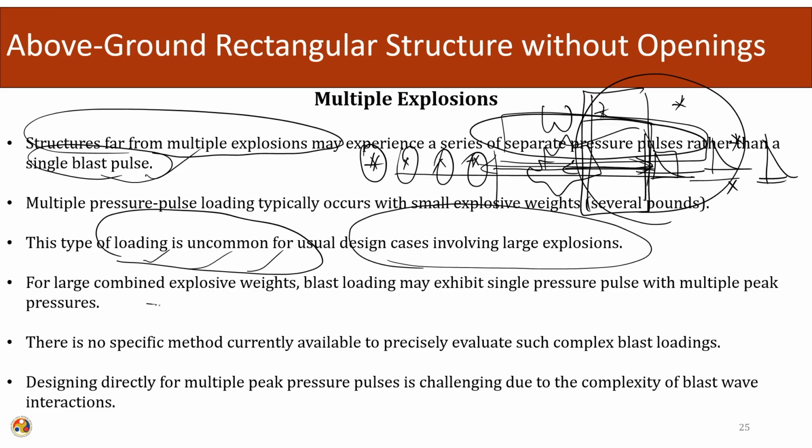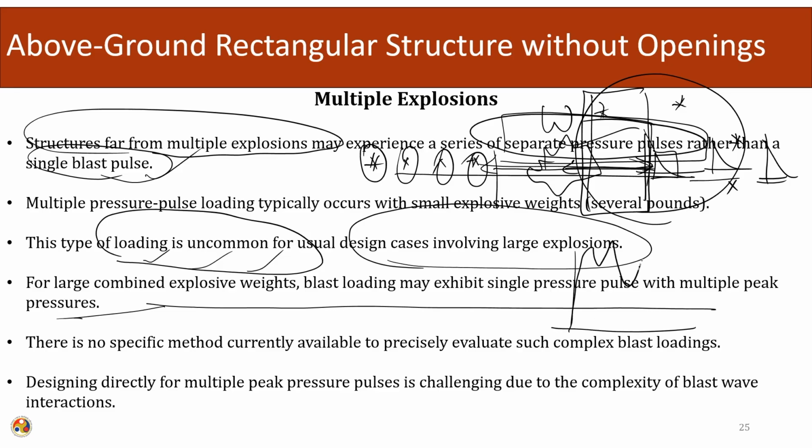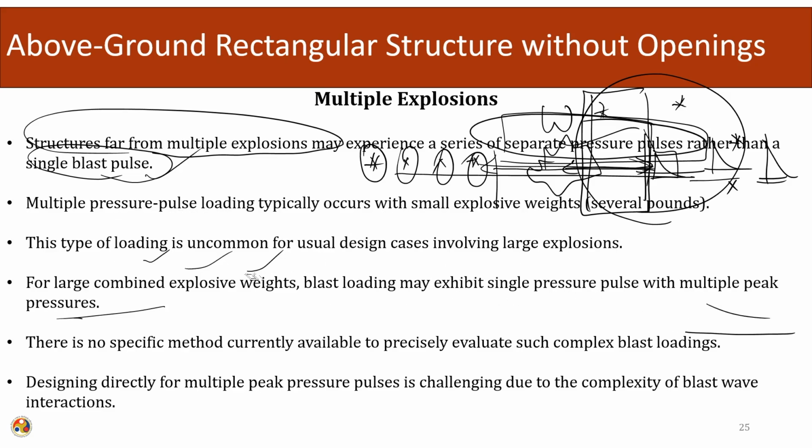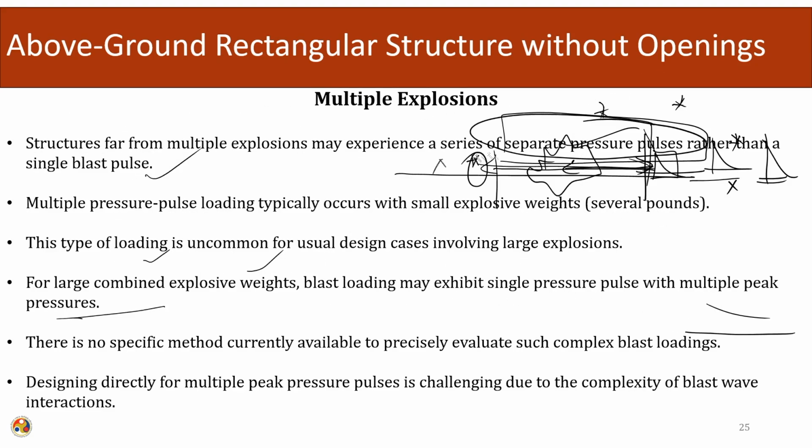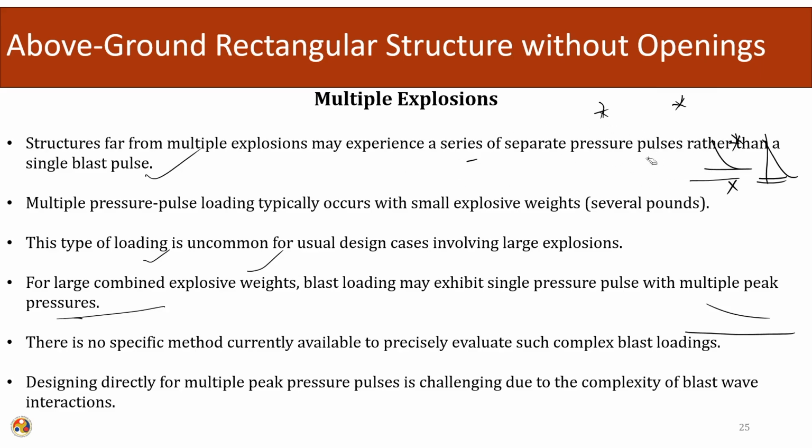For combined explosive weights, blast loading may exhibit a single pressure pulse with multiple peak pressures. It means that the loading is combined, but it is peaking at different instances. So, there is no specific method currently available to precisely evaluate such complex blast loading. Blast loading in itself is very complex.